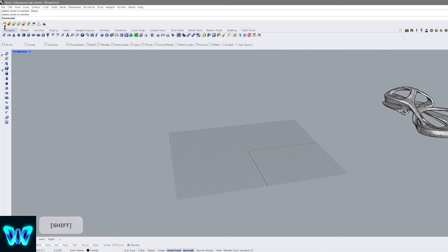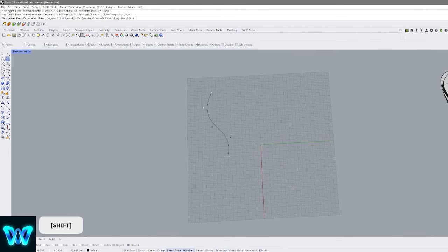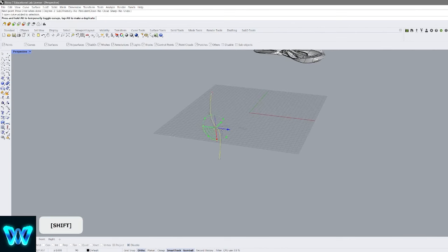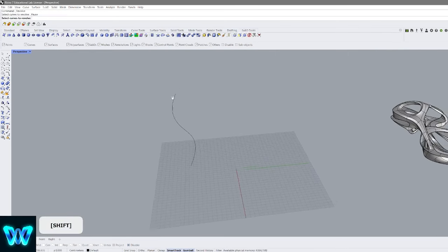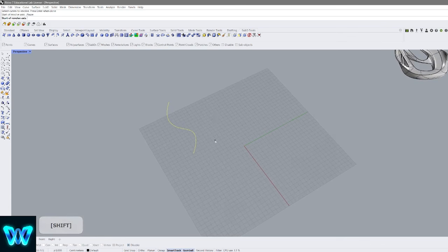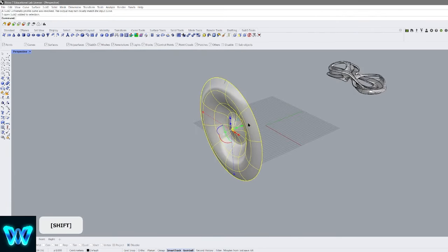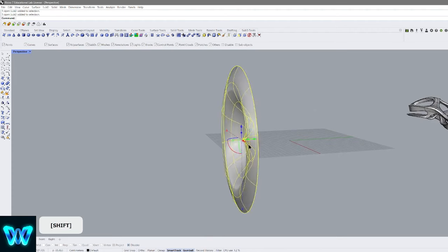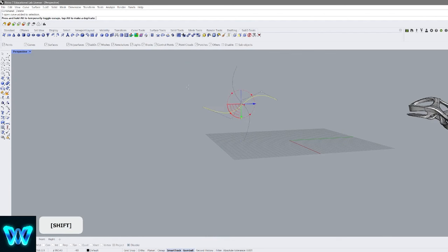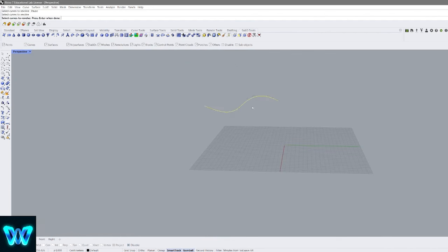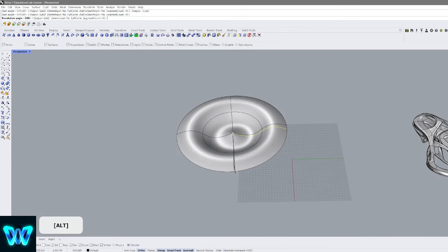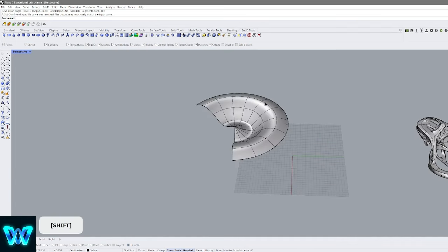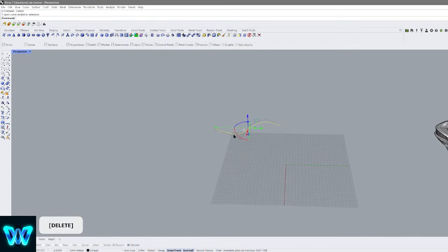This pretty much just uses a curve. So we're gonna start with a curve, right? Whatever a curve is, we're gonna flip it, move it up a little bit, and what SubD revolve does is it revolves around it, right? So the axis could be the center, whatever. Actually, it flipped it, but then as you turn it, you see that it just creates a revolution around it. Actually, what I was trying to get at probably would have been done better this way. So revolve, whatever, pow, and you can see how you can revolve around it. I've never really used this one, but for specific cases, this is probably really useful to create specific pieces, etc.